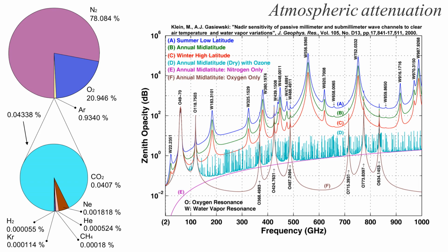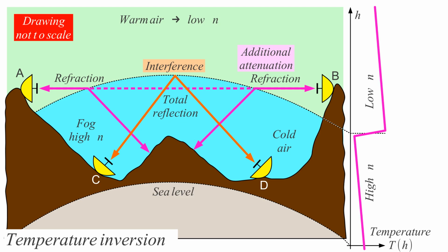There is not just the loss in the atmosphere, that's also another effect. Another effect we have here, besides loss, is the refraction index. I cannot cover the whole refraction index. I'm only going to give here a rather nasty example of what can happen with the refraction index. The refraction index always decreases with altitude, because the air becomes much rarer at altitude.